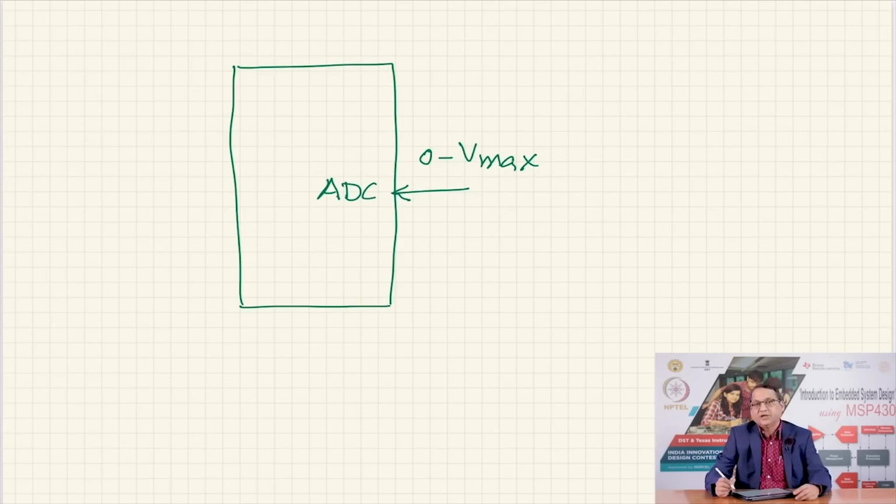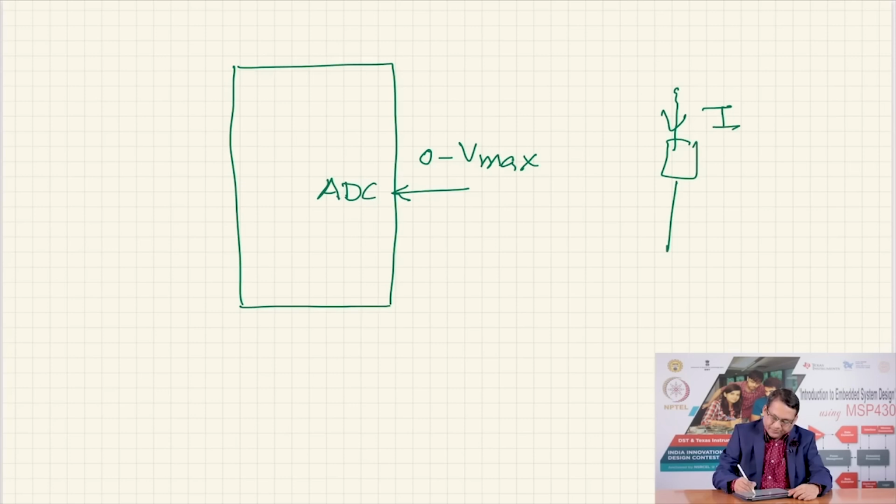And now instead of measuring voltage, I want to measure current. Now current obviously would be passing through some circuit, maybe I want to measure this current, and I would use the same mechanism that a multimeter, an ammeter for example, uses to measure current. And what I would do is I will introduce a very small resistance R, very small, so I designate it as R low. The voltage that is generated is so small that I do not get enough resolution for my ADC, so I put it through an amplifier